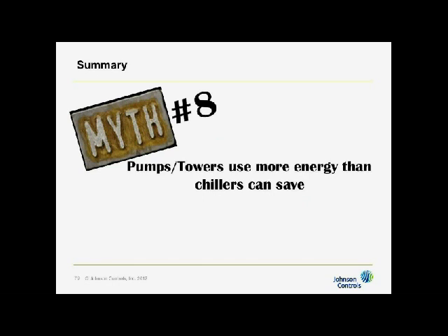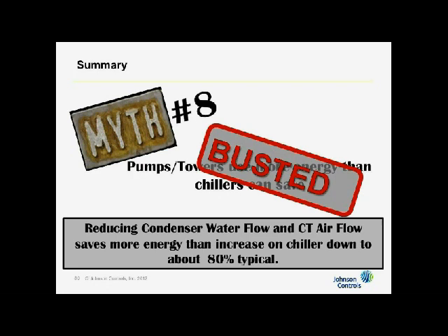Myth number 8, pumping towers uses more energy than chillers can save. And we busted that. We have proven that reducing condenser water flow and cooling tower airflow can save more energy than the increase in energy on chillers, down to around, at least for the case that we chose, 80% of full design flow.